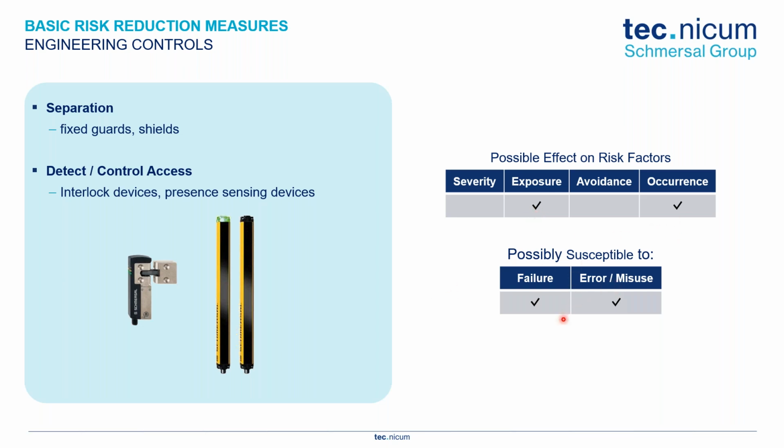However, we may be prone to failure and misuse, okay? Because we can take a safety function and wire it incorrectly, right? You can program an incorrect program for a safety PLC. You can maybe remove a guard if we're not using the right type of fasteners, okay? So between misuse by the operator, perhaps, or failure with the system.